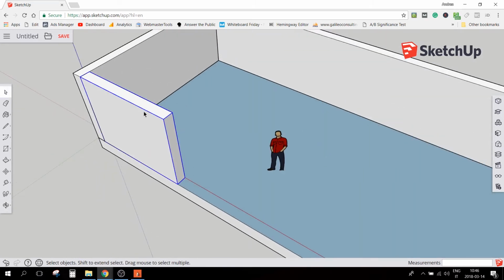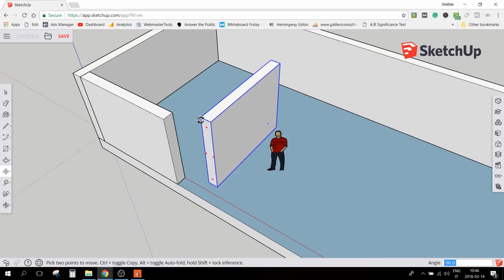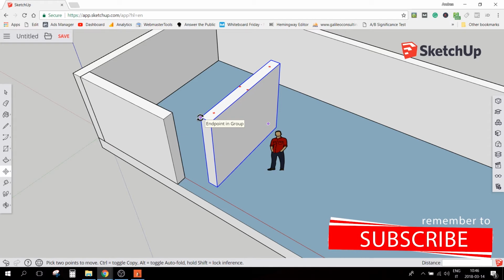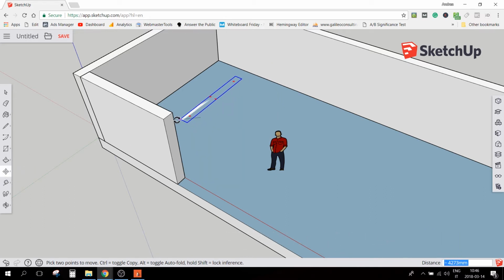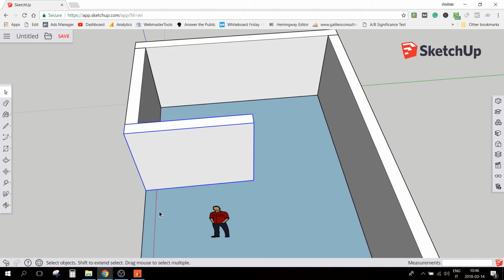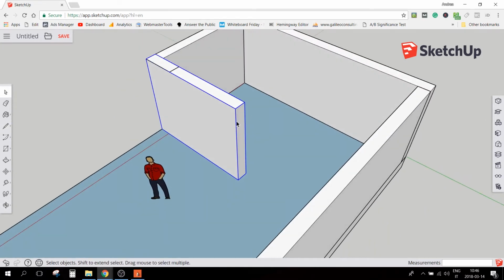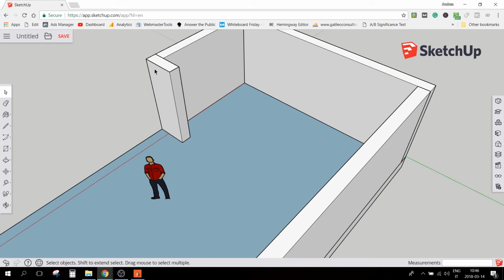Now I want to take this, Ctrl C, I want to turn it 90 degrees, take it from the corner, sorry, take it M, take the move tool, cut from here, and okay. So now I will measure from the outside 1000, and here I'll draw this little line here. Now I open this object and I push it back to the line here, boom, and it snaps on the line. So I have to delete these 2 lines I made.